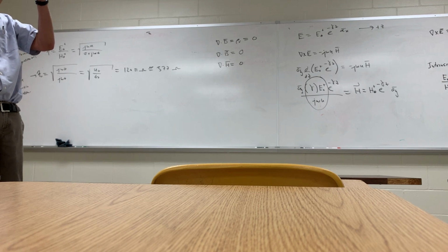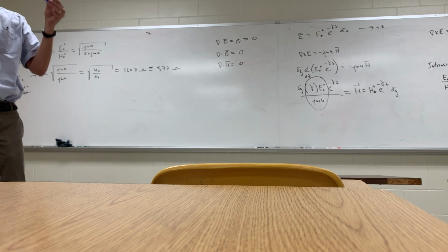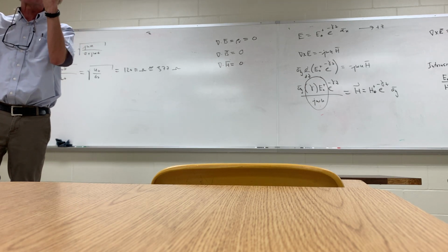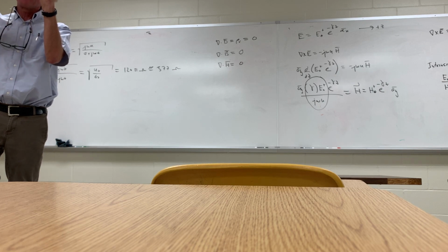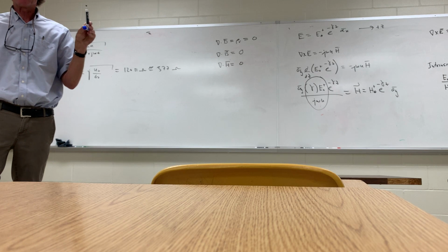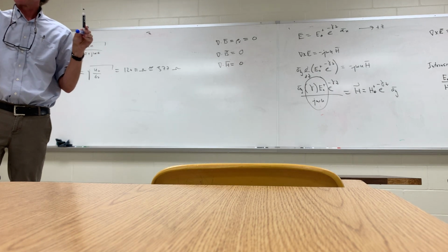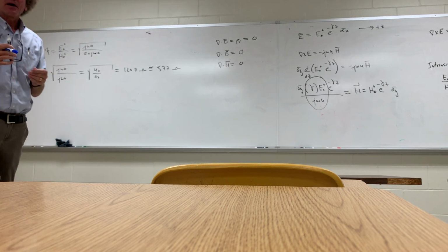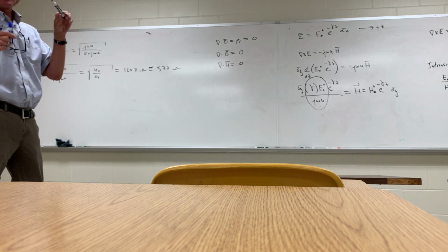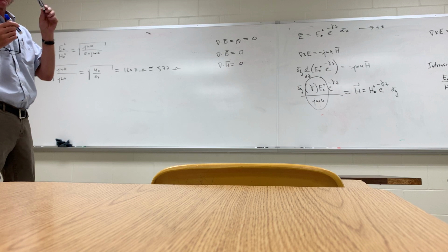And whenever you have E and H field propagation, if you take your right hand, assuming you have one, and put your index finger in the direction of the E field, and then just turn the door open into the H field, your thumb will point in the direction of propagation. How many knew that, by the way? I know you better have done this. Yeah, that's something to know. We'll get to that later with power, but E cross H is always the direction of propagation.